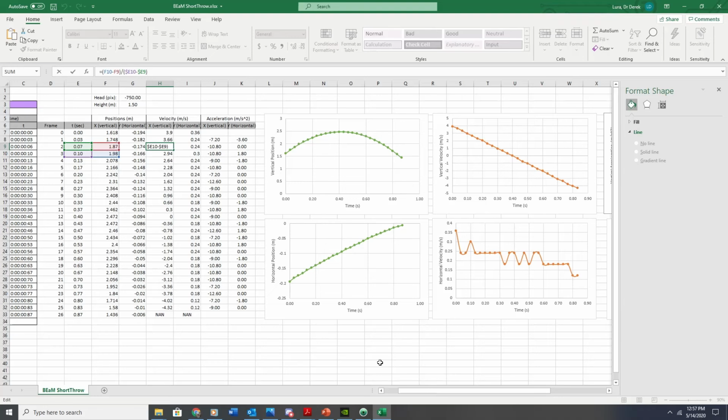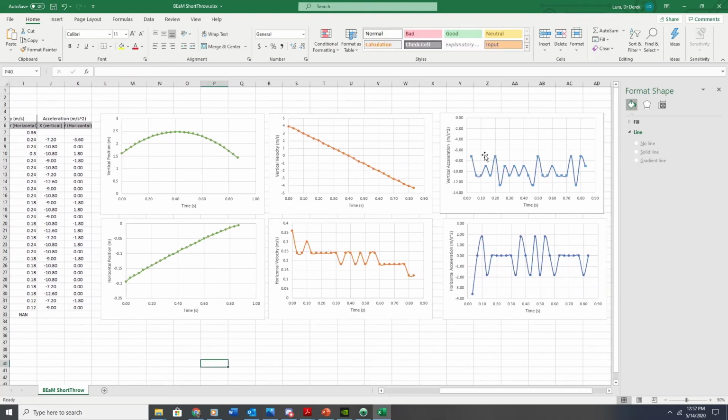So one of the things we can do is filter this data to smooth that out and get rid of some of these jumps. But the higher order derivative that you take, the more significant those are going to be because of the properties of the derivative. So keep that in mind. If I were to go to jerk, which is the derivative of acceleration, then this would get even more significant, and the amount of filtering would be more.